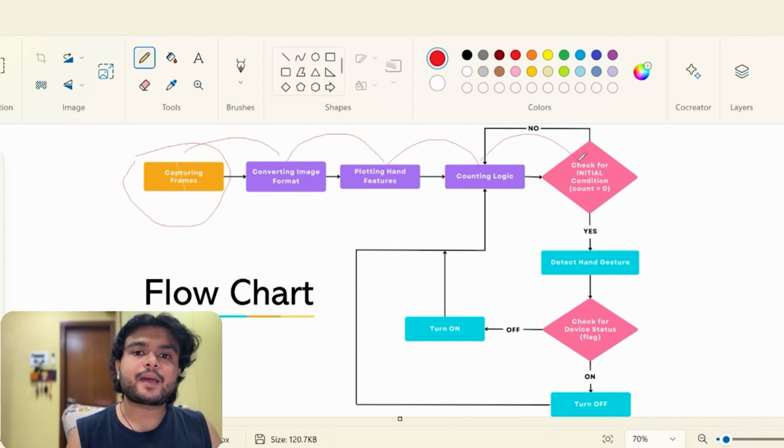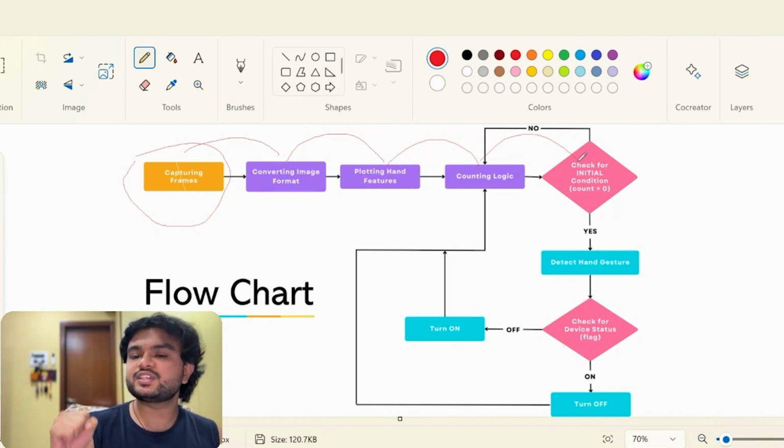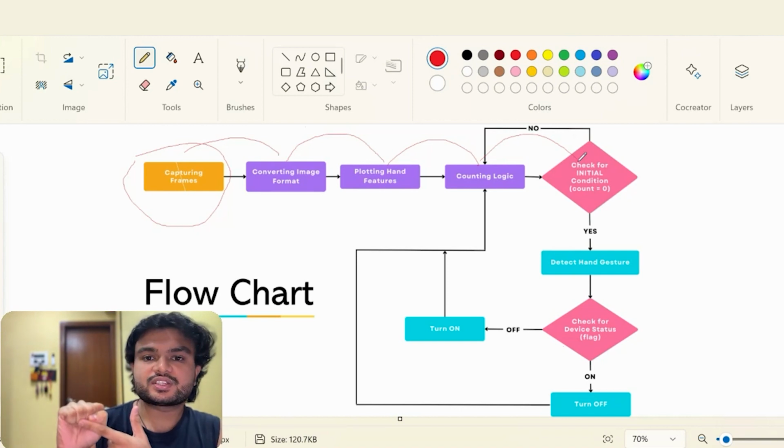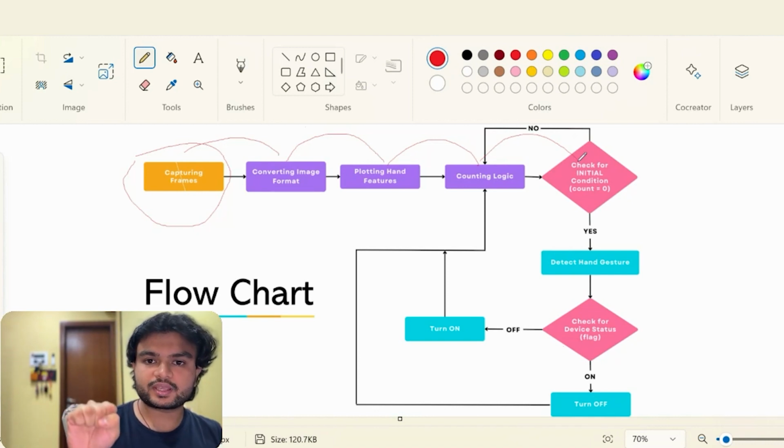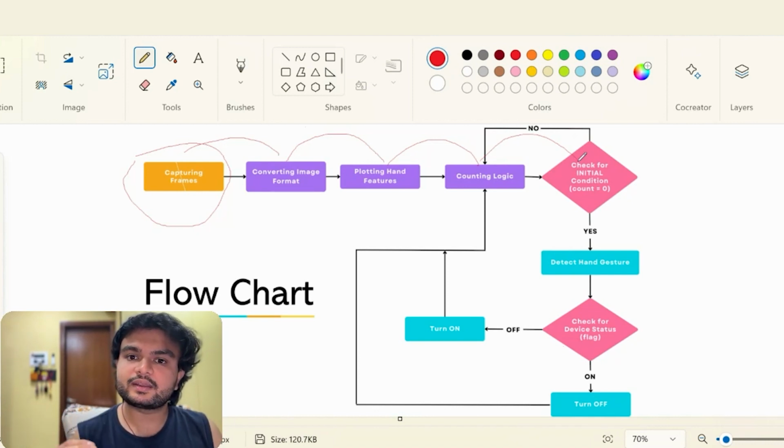It prevents any mishaps from happening. What can be the mishaps? For example, if you're trying to ask someone to get you 2 books, the camera will not understand whether you're telling the product or someone else. So for the camera to understand, we have put in a basic initial condition. It needs to recognize a fist condition before you enter your gesture for recognition. You have to show your fist to the camera module for about 3 seconds, after which you are entitled to show the gesture. If you don't enter the gesture within 5 seconds, then the machine will go back to its scanning state. This is used to prevent any mishaps from happening.